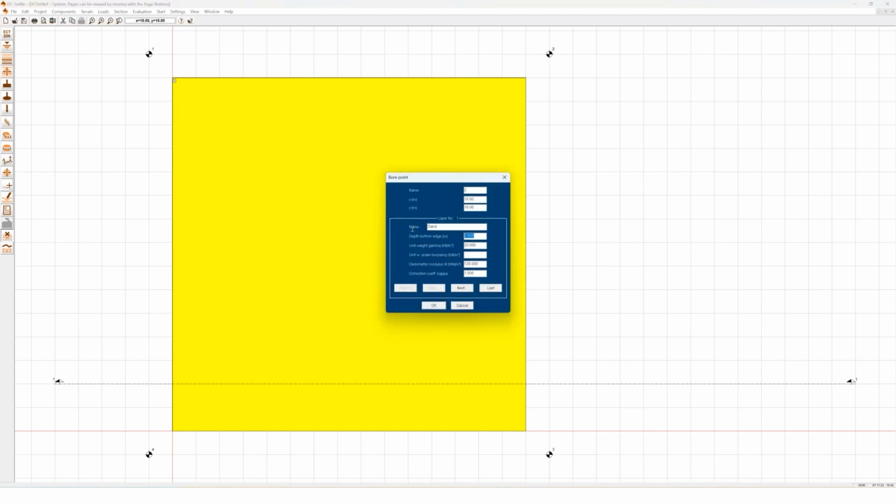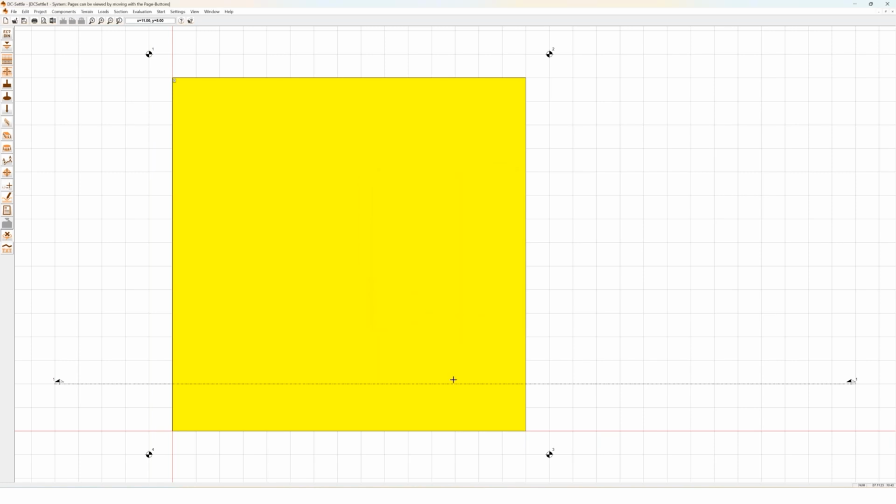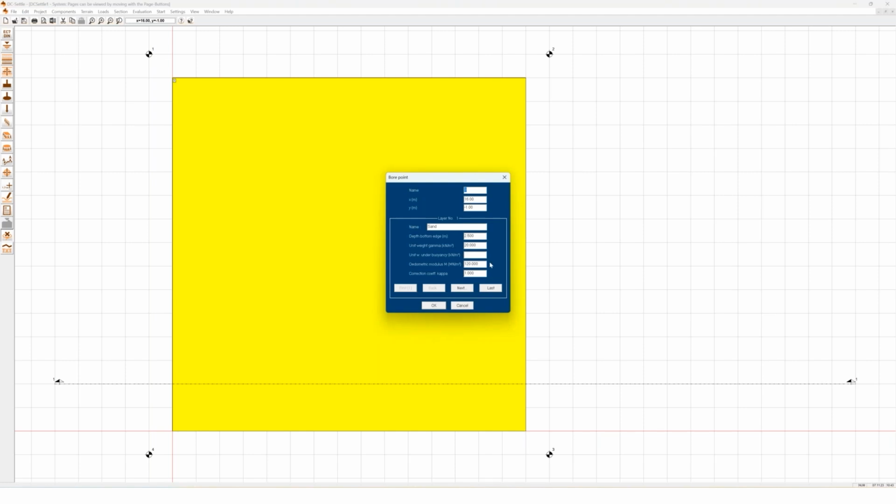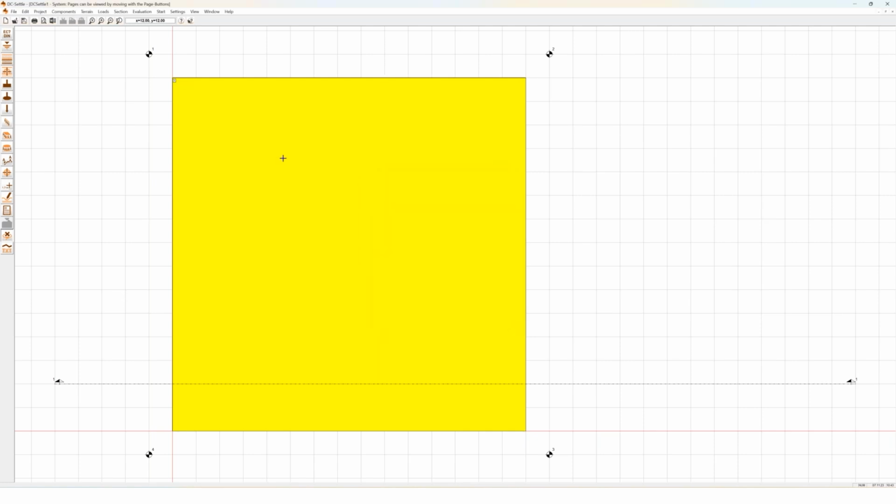Then we have the second one. And here we say we have a greater sand thickness, which is 3 meters. And then we have 3.9 meters, the bottom edge. So we have 90 centimeters silt. Say apply. And the third one is sand with 4.3 meters, and the silt is just 20 centimeters. So we have 4.5 meters. Apply. So we have different layer thickness, and we see this now in the graphic.